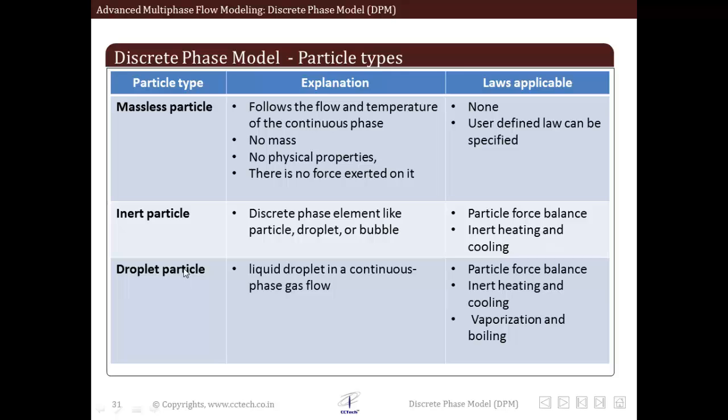The third type that we will discuss is droplet particles. These are liquid droplets in a continuous phase flow. Particle force balance is applicable to this. Also, inert heating and cooling laws are applicable. Also, we can model vaporization and boiling.